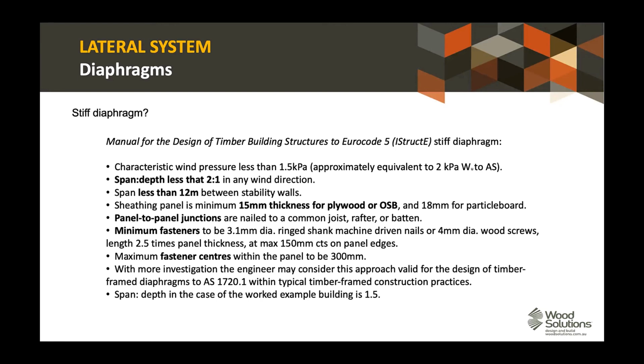Well, if you don't have a stiff diaphragm, you've got all kinds of complexities with working out your load distribution between your bracing system. Because as well as working out individual wall panel stiffnesses, you then have to work out how the stiffness of your diaphragm varied along its length to then distribute load in between your stability walls, which gets really complicated, given what we know about calculating or estimating stiffnesses of systems.